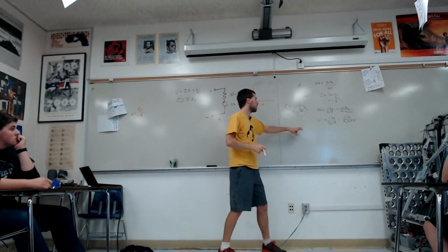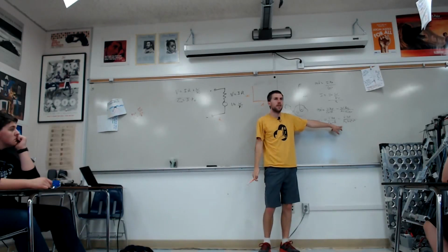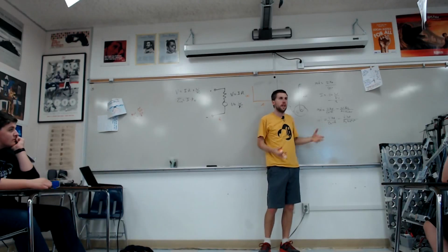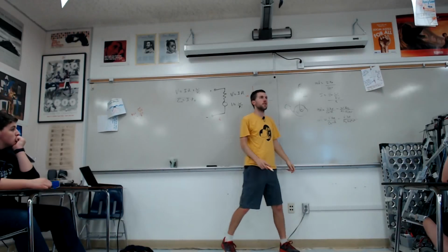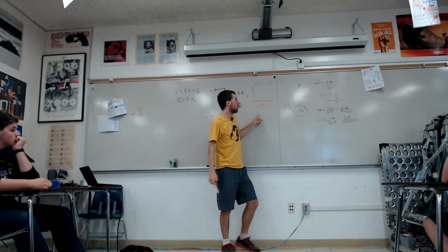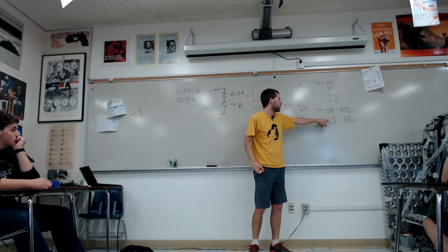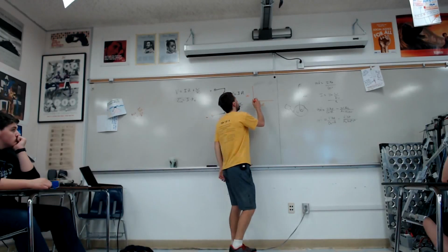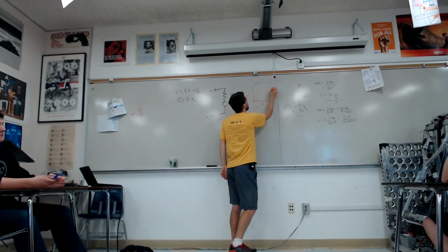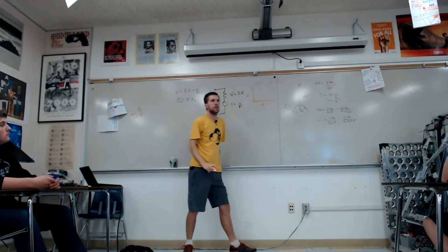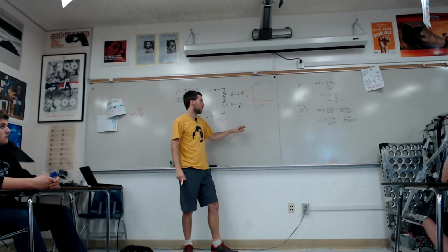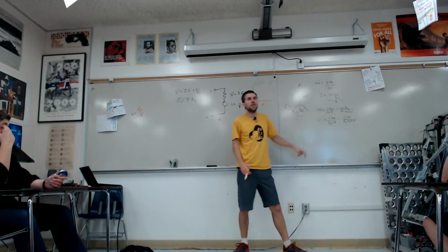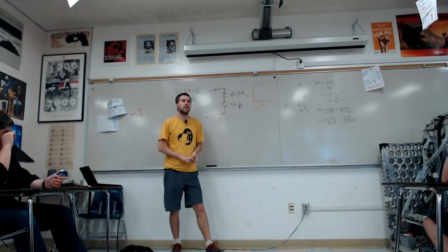Intuitively, what this is saying is the position of our elevator doesn't matter, which makes sense. There's nothing physically different about being in different positions. What we care about is when I apply a voltage, how does the velocity change? How does it accelerate, decelerate? This is going to be an exponential decay up to your free speed. And the rate's going to depend on the mass.